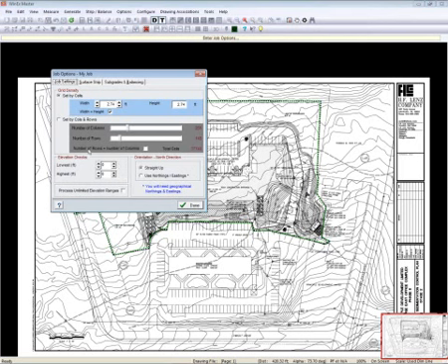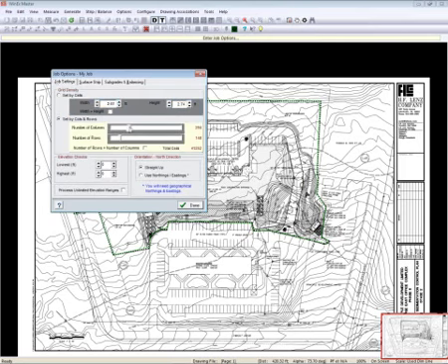And a couple of things I want to explain to you here. If you remember earlier, I mentioned to you that you can put up to 1 million cells on the site. Based on the scale, it has set us up at around 37,000. I'm going to set it so that I'm going to work at a lower width and height right now. So I'm going to adjust my height first, and bring it down to maybe just a little over 1.5 feet, and I'm going to do the same on my height, bring it down just under 1 foot. And again, you can change this on the fly as you get towards the end of your takeoff.